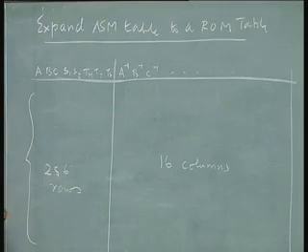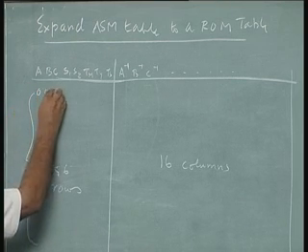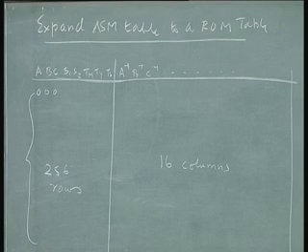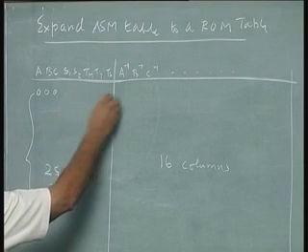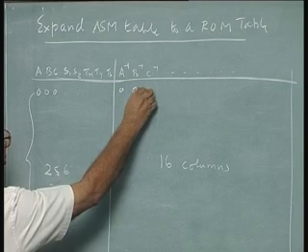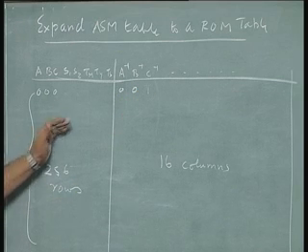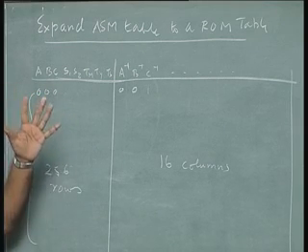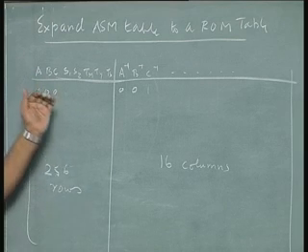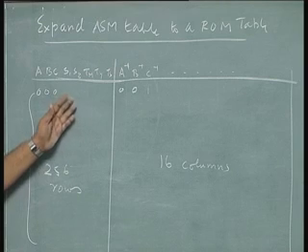But the ASM table has been expanded. For example, the 000 state, whatever is the condition, goes to the next state 001. I am just telling from memory, please refer back to your notes. In the S0 state there is no condition, you always go to 001, and what is the output in the state?